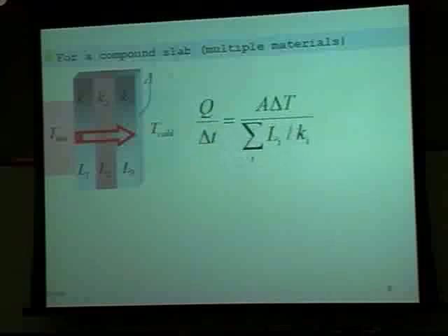as this. The amount of heat per time would be, it's kA ΔT over L, but I took the K and put it in the denominator because I have three different intrinsic materials, and each material has a different length and a different conductivity. So instead of having the K up top, we're going to divide by the length divided by conductivity for each material in the denominator.